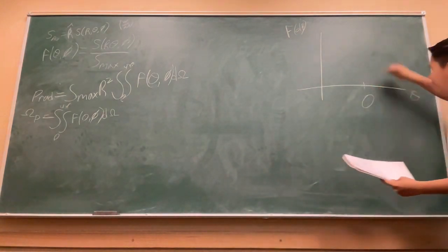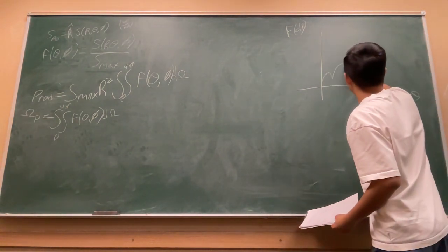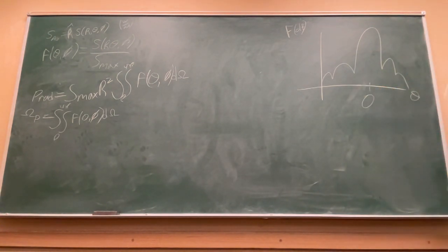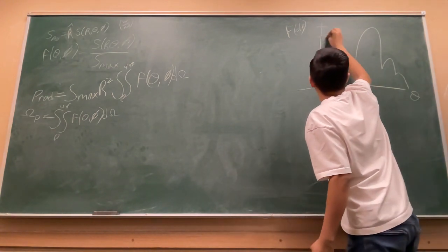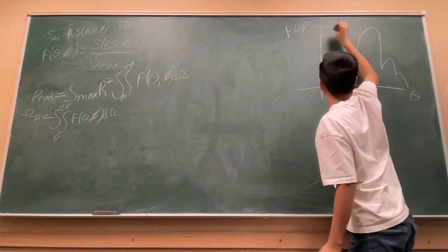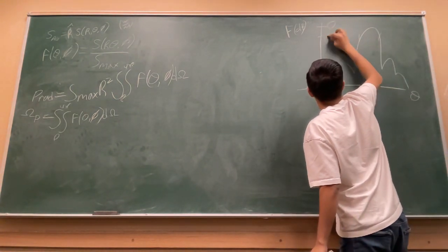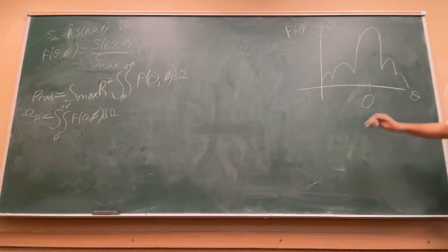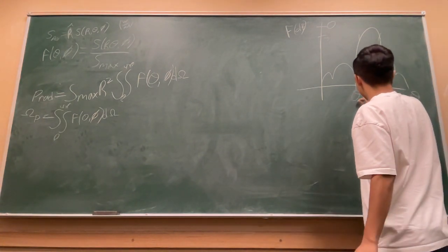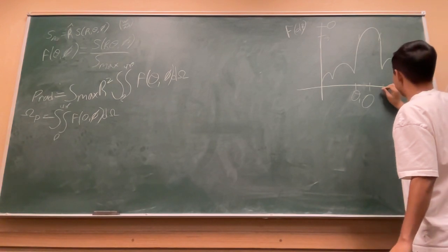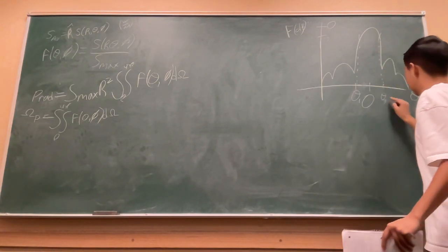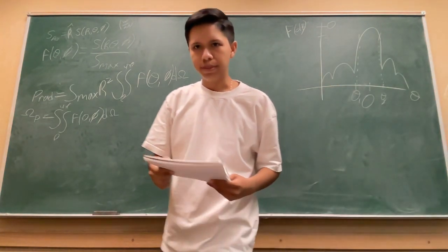So we have this plot. From this plot, what we're interested in are the points that are 3 decibels less than the top of the plot, which is 0 decibels because this is normalized. So we're looking for something that is 3 decibels less, and that'll give us the half power. We're going to call that the half power beam width, with these being the half power angles right here, the angles that correspond to these points. Okay, so that would be the half power beam width.